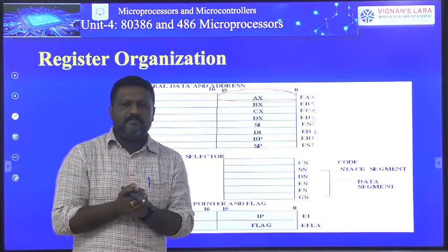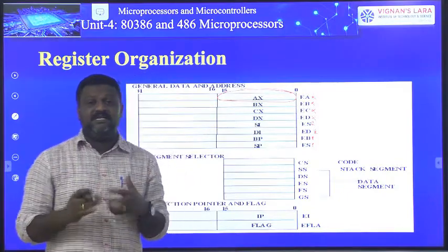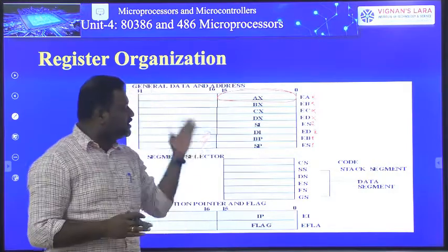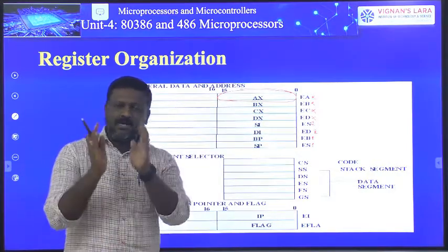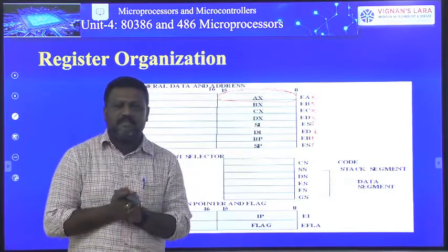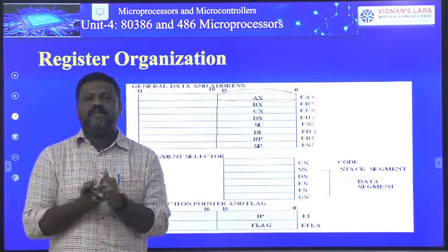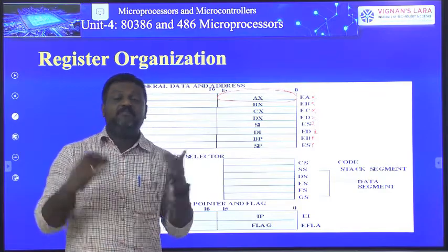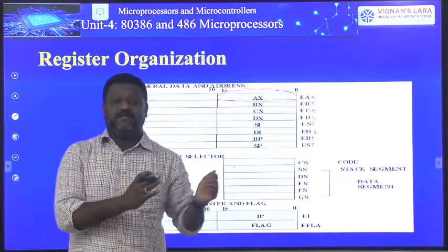At the same time, my 80386 sometimes can do operations on 8 bits. That time I don't use either 32-bit registers or 16-bit registers, I just want only 8-bit registers. So in case of 80386, I am able to get 8 8-bit registers.